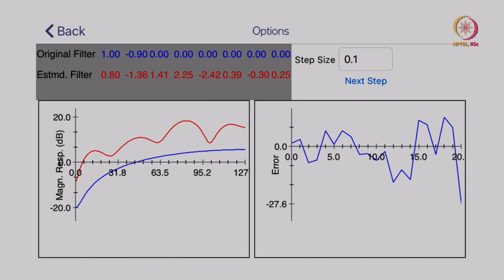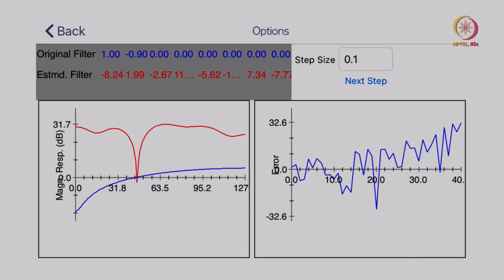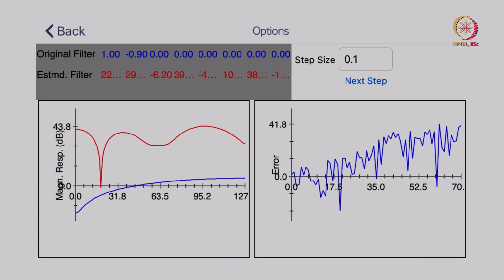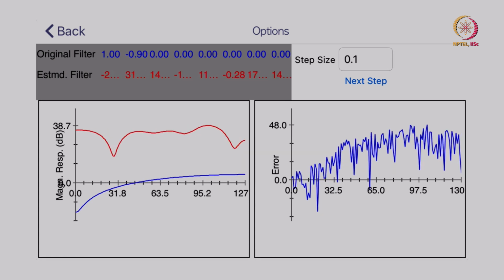So, by default, what it has taken. We will see with 0.1 as a step size; it was 0.05 earlier, now it is 0.1. You are seeing that it is going into the negative. What is happening? It is not reaching 1.0. They are varying much away. By varying your step size, with a smaller step size you will see that it gets adapted, and then by making it a little more, you can see that it is oscillating between the positive and negative side.